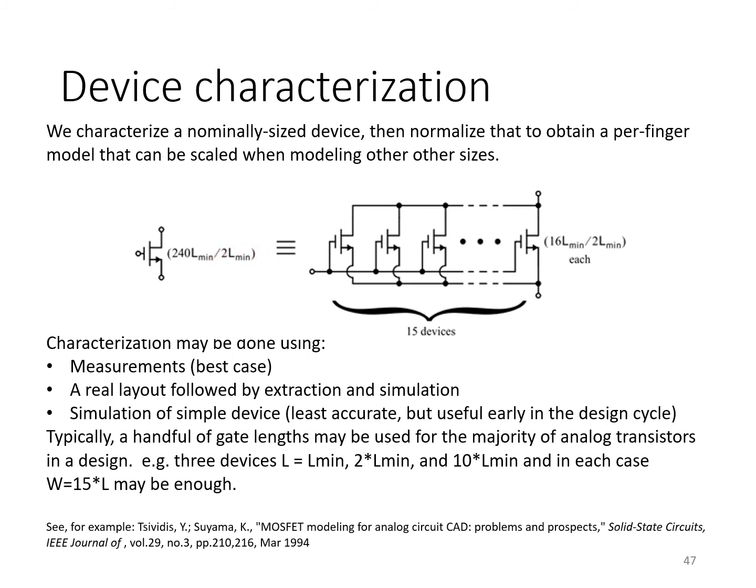And the reason is that often at the very, very minimum gate lengths of any technology, especially those in 180 nanometer gate lengths or below, you often see changes in some of the model parameters. So you don't want to apply model parameters that are extracted with minimum gate length devices to non-minimum gate length devices. So you might create a couple different test benches.